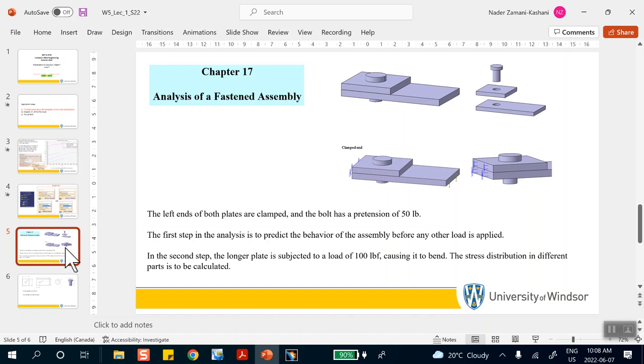You don't model these bolts, because imagine that it's so tiny here. If you wanted to model this thing, you'd need tiny little elements, of the order of maybe 1/10 of a millimeter, and then that has to connect with something here, which is probably shell. The surface of this is shell, etc. But the point is that you don't always model bolts. But I want to show you what happens if you did want to model it. Maybe you are in the business of designing the bolt itself.